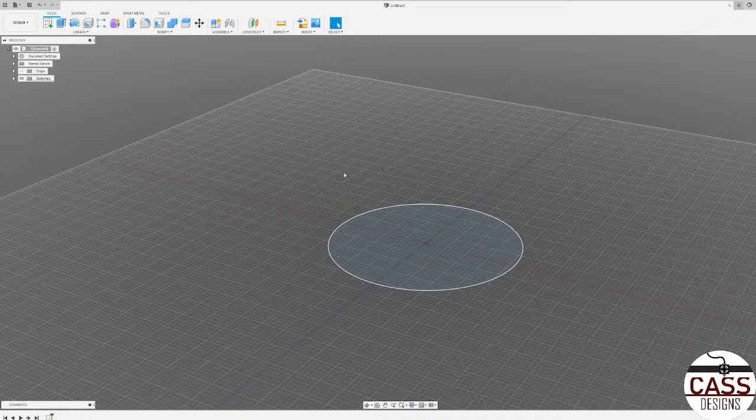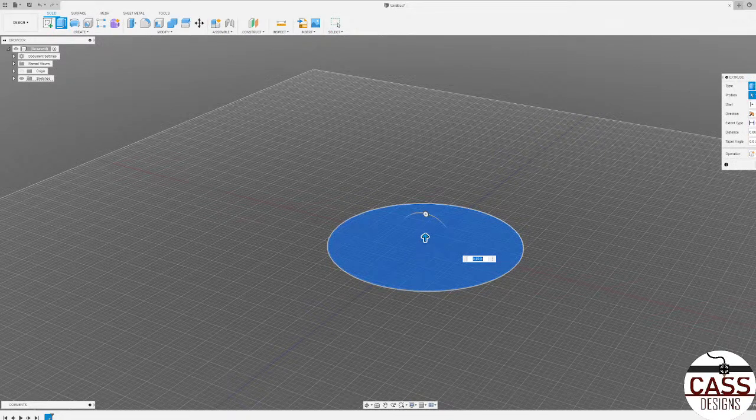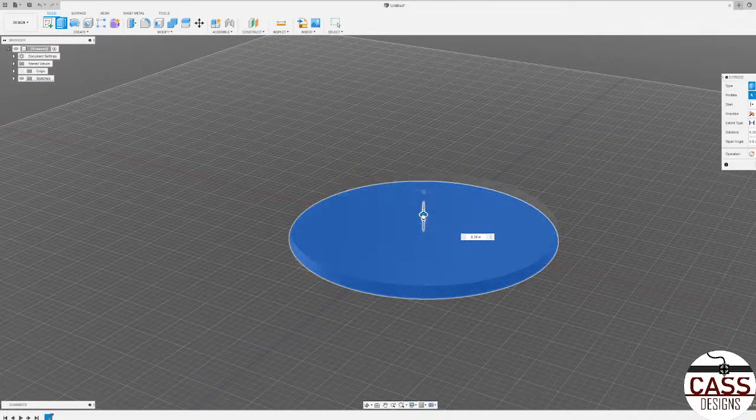All right. So now you can see up here there's Create Sketch, Extrude, Revolve, Hole, and all this other stuff that we'll eventually, hopefully, get to. The next thing we want to do is extrude this. Here it says for type you have extrude or thin extrude. Thin extrude basically grabs a thin feature of the sketch and extrudes that. But what extrude means in general is it takes the area of a closed profile and drags it to create a 3D model. You select the profile you want, and since we only have one profile, it auto selects that, since it knows this is what we're trying to extrude.